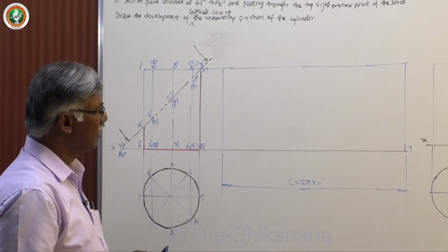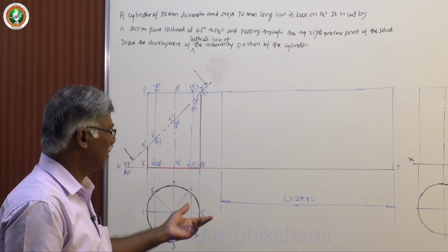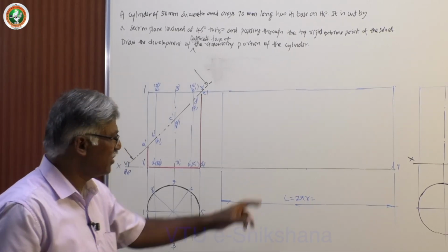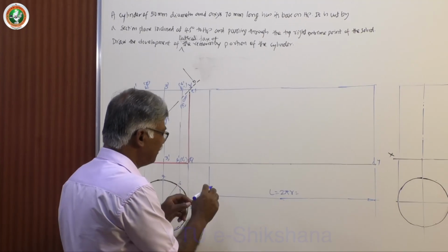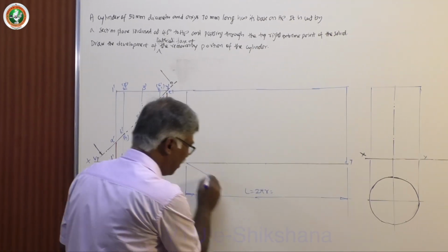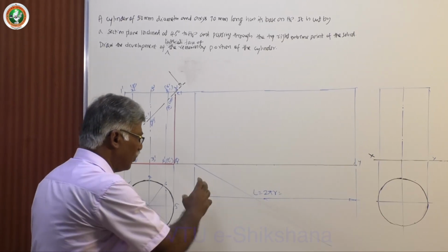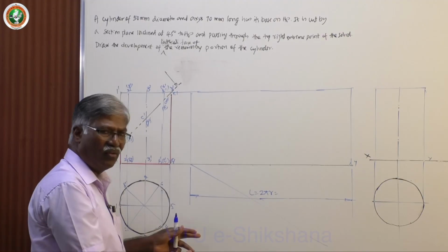Next, there are different methods of dividing this. If you are working manually, you can divide this into n equal parts by taking an inclined line from this, approximately 30 degree to 40 degree, whatever. So, you calculate this total pi r, you will get some value.